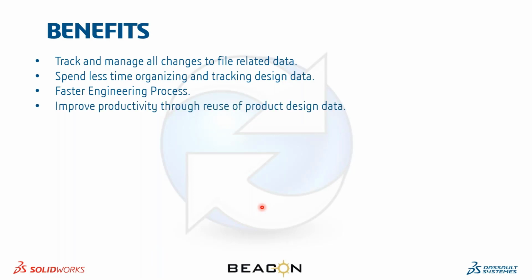Next is having improved productivity. Since it is all interconnected, we will have better productivity because we're sharing the latest files, and we can automate the sharing of files to production. Once the file is released, PDM will automatically take care of converting them to PDF, or a model into a STEP or IGS. It will be shared with them through a notification, and they can directly access the files in their shared drives. When I say shared drive, it is within the PDM environment and not shared drives like Google Drive or Outlook.